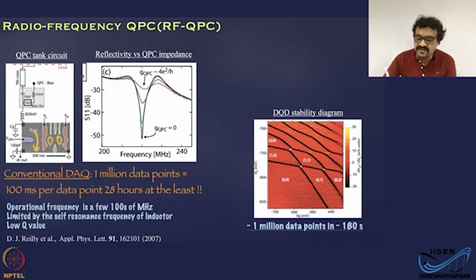And as we discussed in the double dot session, the double dot is going to give you a charge stability diagram, which is going to look like a honeycomb. So this region is 0, 0. And as you go either horizontally or vertically, you are going to fill one of the dots in. This is the typical charge stability diagram for a few electron double quantum dot. Usually, you get this information by measuring the direct current through the device.